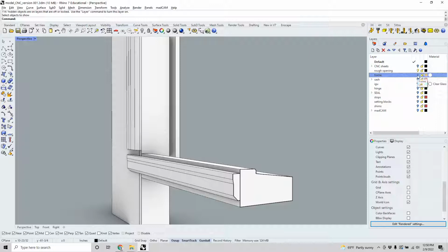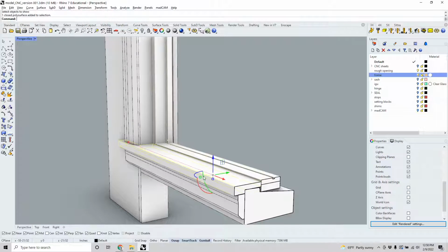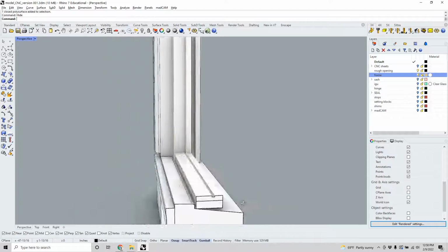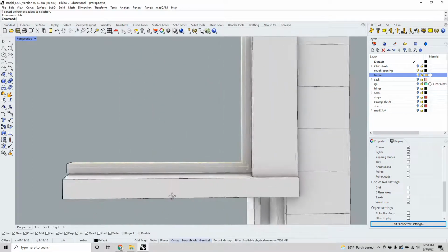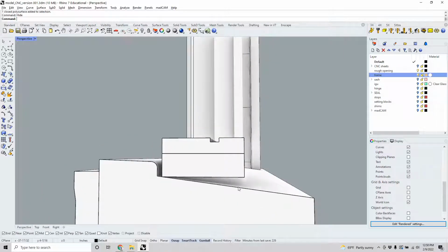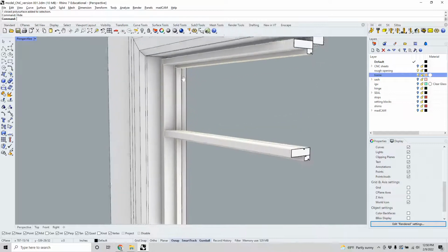All right, let's take a look at the frame of the window. This is that new sill that I was talking about. Let's go ahead and hide that so it's out of the way so that we can see only the frame. The frame essentially sits in the rough opening. There's a gap here, so I shimmed that later on with some custom shims that I 3D printed using this exact slope of this pitch here to fit that in. This is going all the way to the top.